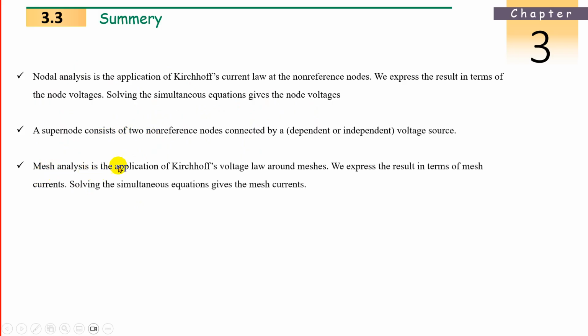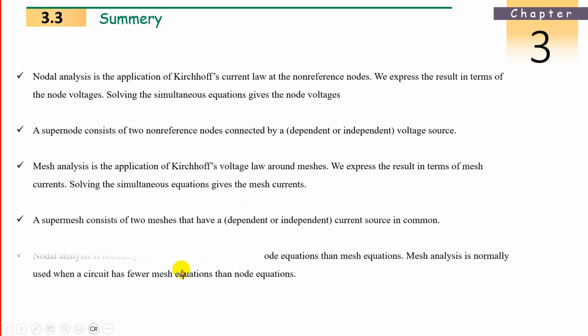Now mesh analysis is the application of Kirchhoff's voltage law, like here current law, here voltage law, around meshes. We express the result in terms of mesh currents. Here node voltages, here mesh currents. Solving the simultaneous equations gives the mesh currents. So here again, supermesh, no need to study.